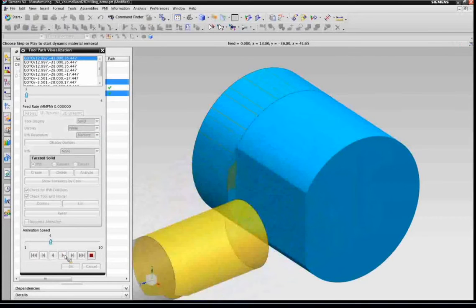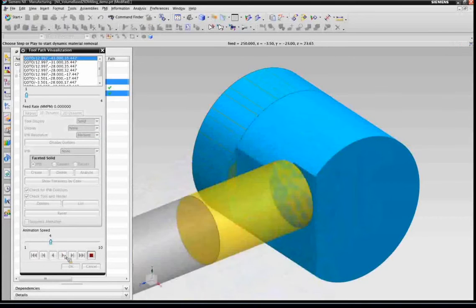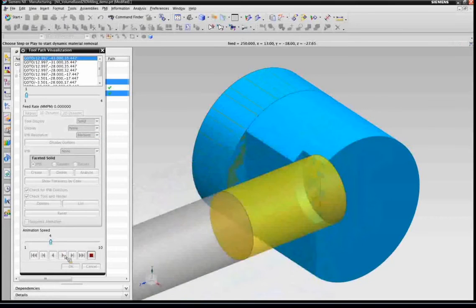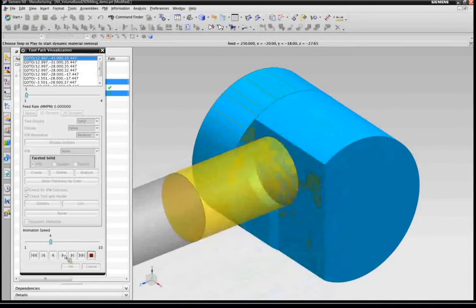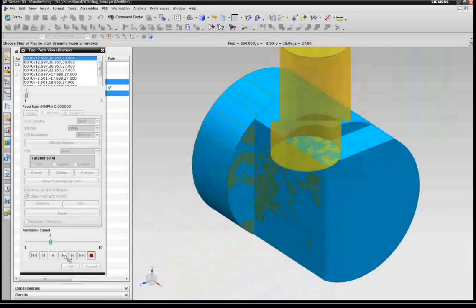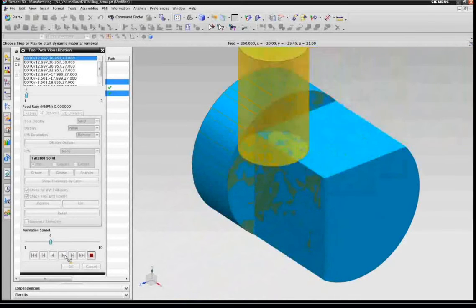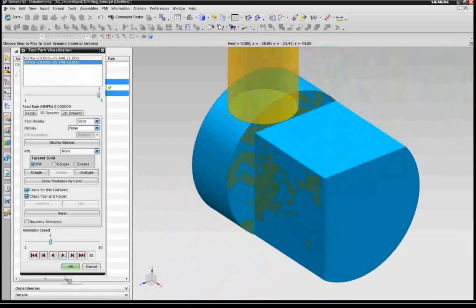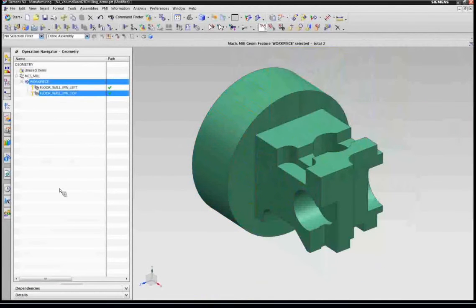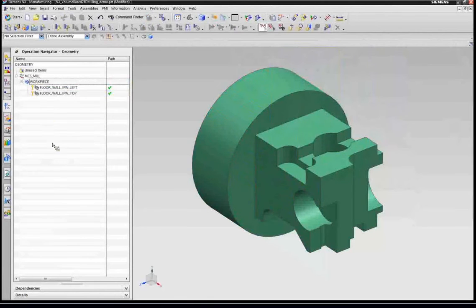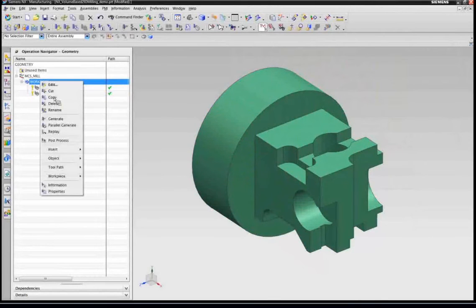So I'm going to cut the left portion of the part first in 3 cut levels without cutting any air whatsoever, and then I'm doing my roughing operation on the top, exactly 2 cut levels, and I'm leaving a mil of floor stock.